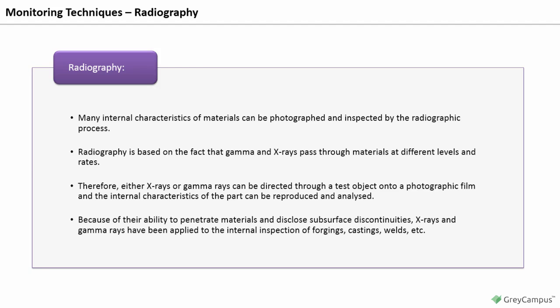For proper X-ray examination, adequate standards must be established for evaluating the results. A radiograph can show voids, porosity, inclusions, and cracks if they lie in the proper plane and are sufficiently large. However, radiographic defect images are meaningless unless standards are used. A standard acceptable for one application may be inadequate for another.